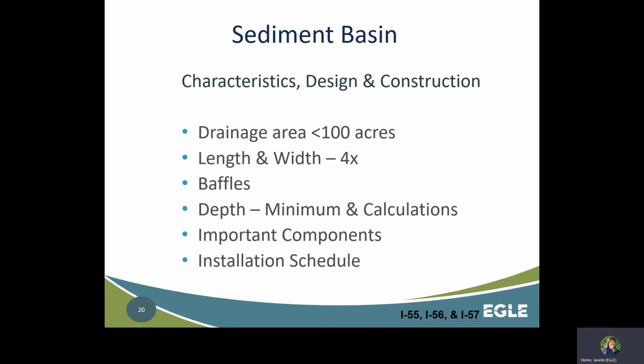Basins are typically used in conjunction with other BMPs. For example, on sites with clay soils and fine silts, a PAM will need to be used in order to settle out these small soil particles. We cannot design a basin big enough to settle out these fine particles naturally.